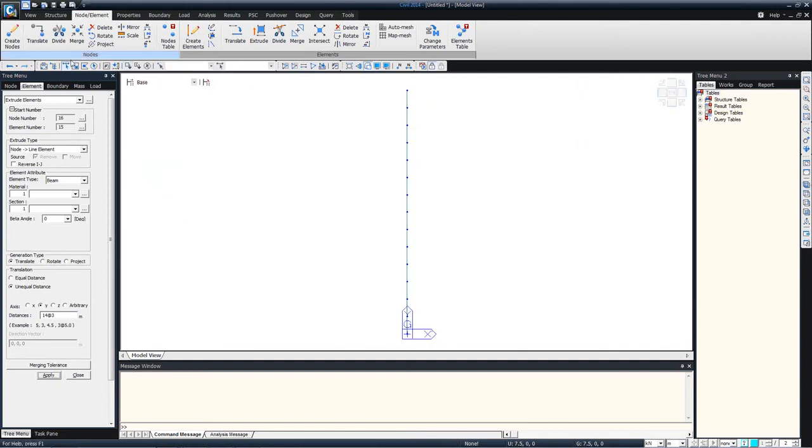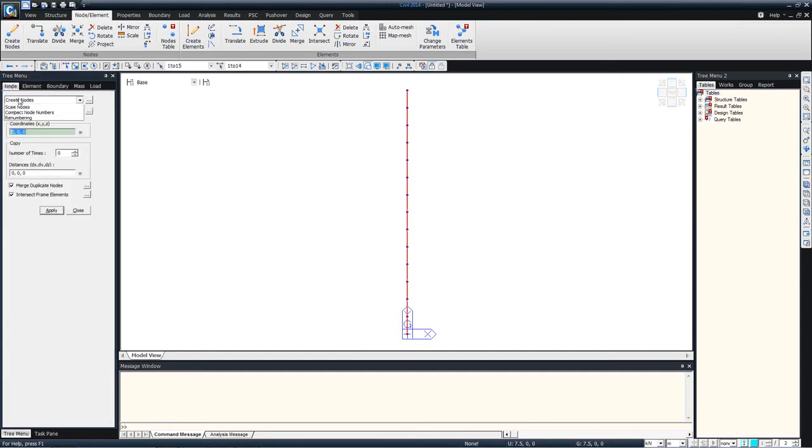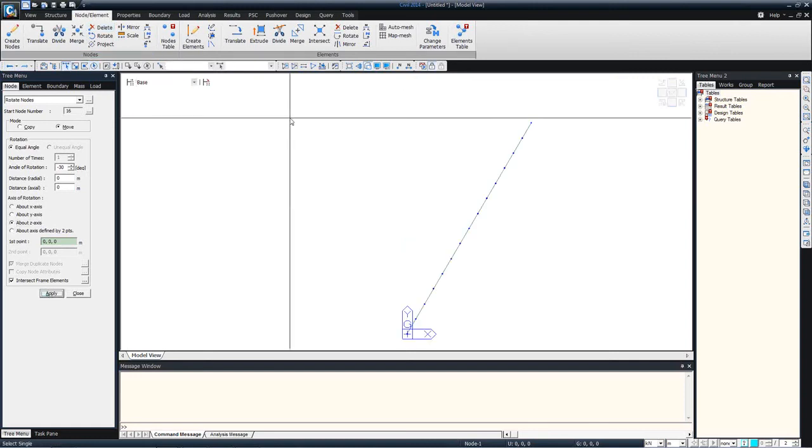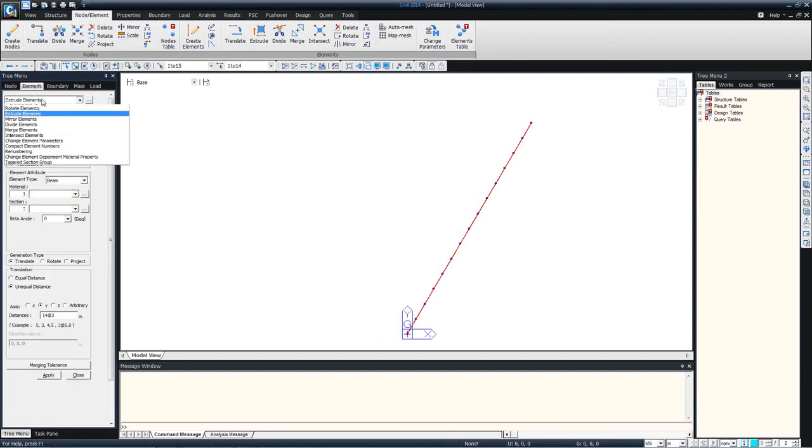And we'll create the skew. So orthogonal grillage involves when you have the skew angle greater than 20 degrees. So let's make it minus 30. Move. Oops, it's in the X direction, Z axis. Select everything, extrude elements in the X direction.